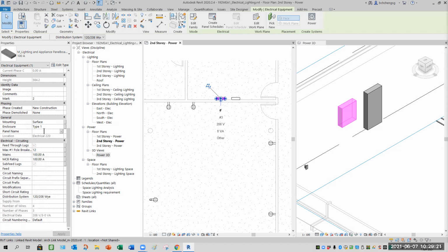So this is PP, power panel 219 for library. Pole breaker, I give it 20, similar to your notes, for room for expansion in case you need to add additional. Always have ample slots for that, remember.